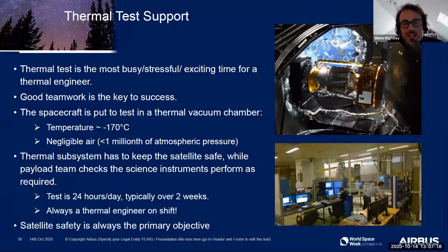We talked about test. Testing a spacecraft, as I mentioned, is one of the most difficult aspects of my role. So when we get the spacecraft to test chambers and we're putting it in, often those tests will run for several weeks, and they run 24 hours a day. You can't pump down the chamber over 24 hours, get rid of all the air, and then recover it again because everyone wants to go home and have a sleep. You put it into that configuration and then you run that test 24 hours a day.